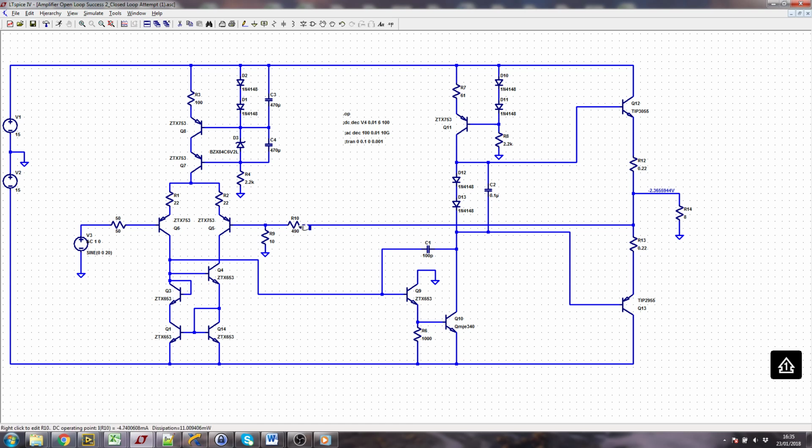But we do want some gain, and it looks like the designer wants the gain to be 1 plus that over that, which is 4.9, 5.96 effectively. So what we could do is make these values considerably larger. The other thing we need to do is to try to make the amplifier have no gain at DC, or unity gain at DC.